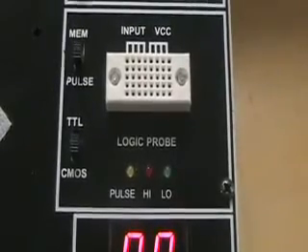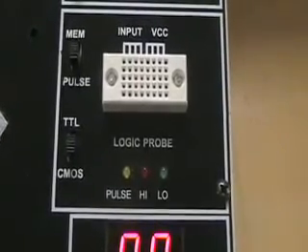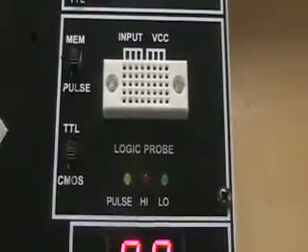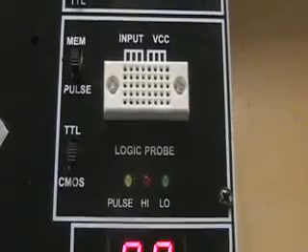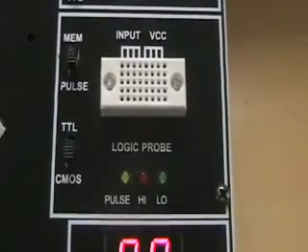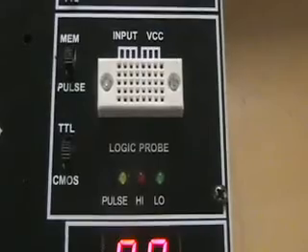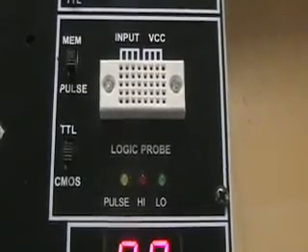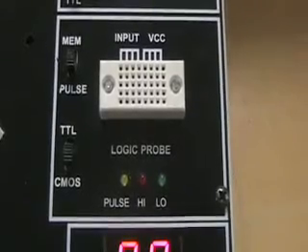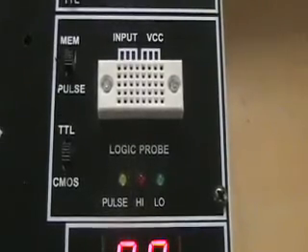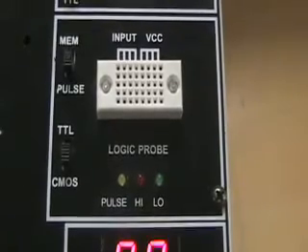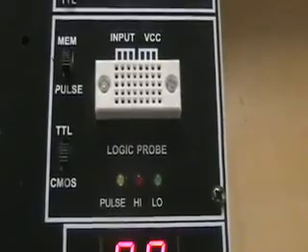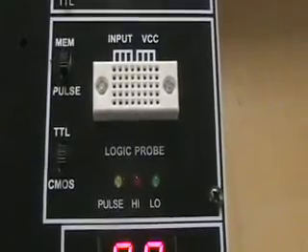The logic probe, located above the 7-segment displays, is useful for troubleshooting your digital circuit. To use the probe, connect the VCC node to the same value of logic 1 being used in your circuit. Most often, this will be 5 volts. Then, connect the input node to the node on your breadboard that you want to test. The bottom switch allows you to test either CMOS integrated circuits or TTL integrated circuits. The top switch allows you to view the change in the value you are testing. Set to pulse, the pulse LED will flash when the input changes. When set to MEM, a change in the input will cause the pulse LED to remain lit.